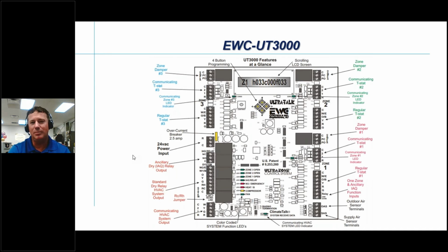And with this EWC zone control, it's using all of that networking to be able to communicate from the zone board into the rest of the completely communicating, modulating equipment. And its input can be based on a communicating thermostat and a non-communicating thermostat. So it can actually use non-communicating thermostats for the basis of the commands for the communicating output signal.